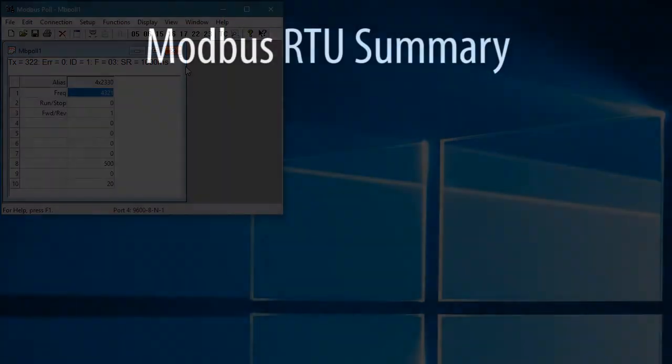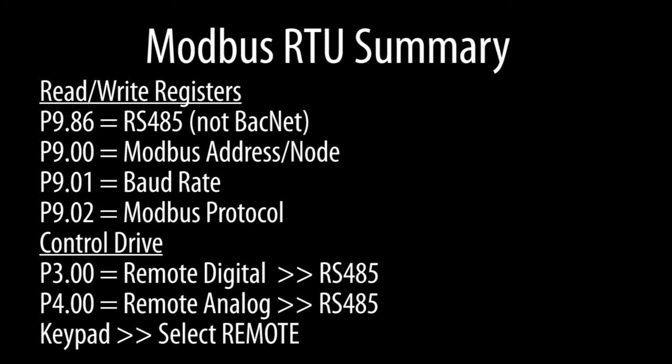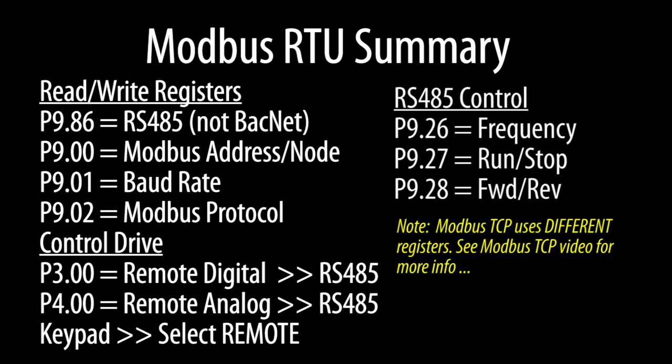Perfect. So in addition to the stuff we did in the first video, all we did was set the digital and analog controls to RS-485 and wrote to these registers to control the drive remotely.